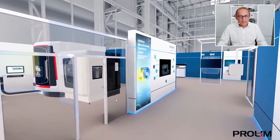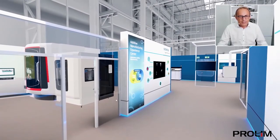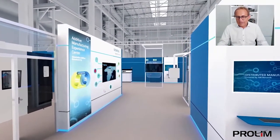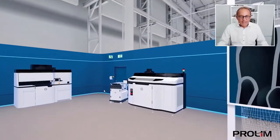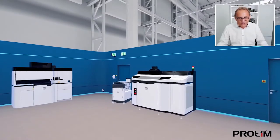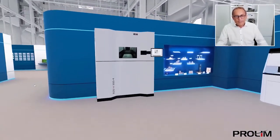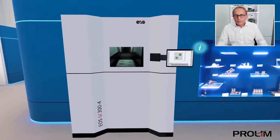Here on the left side, you see the DMG Mori LaserTech 65 3D machine, where we can do directed energy deposition, printing, turning and milling, all completely in one machine. If we go a little bit ahead on our shop floor, you see on the left side an HP machine representing the jetting technology, the newest HP industrial machine, the 5200. And we can also see an EOS machine, an EOS M300. This is a powder bed fusion machine where parts can be printed with metal powder.